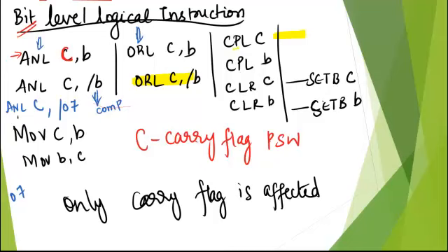So bit level instructions, as I said earlier, will be operated on the addressed bits, starting from 20 to 2F of your RAM memory, and other than that, some of the special function registers which are bit addressable. Okay. So this is your carry flag.